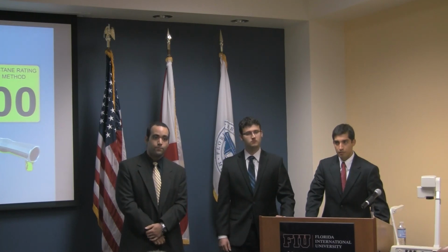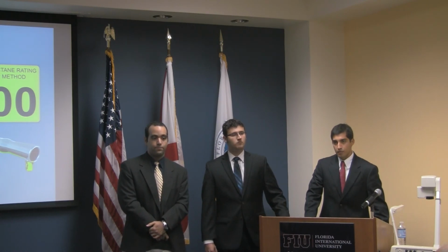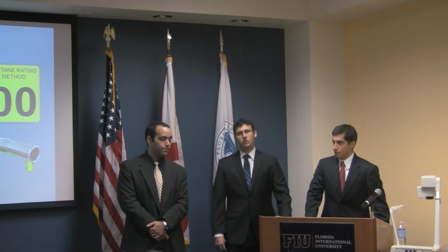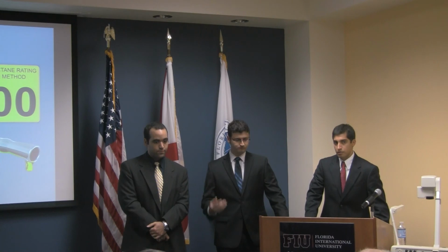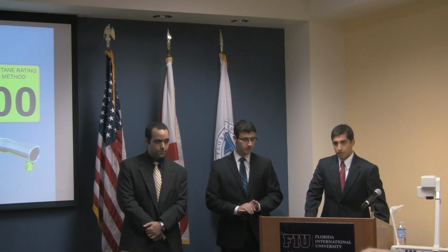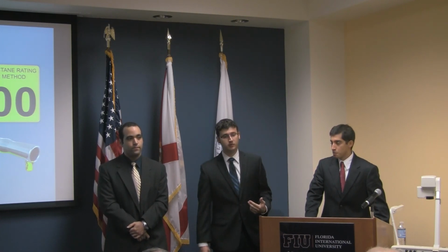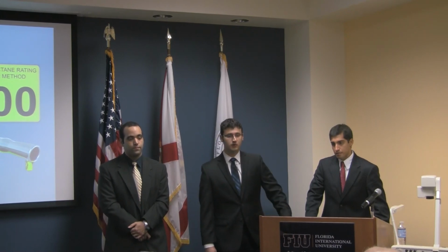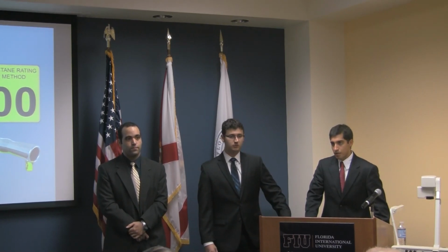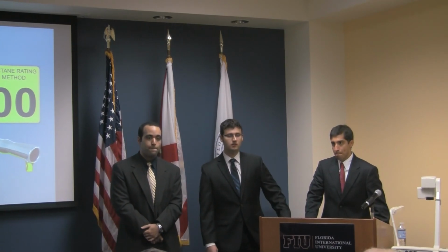Quick question there. So you found it a better option to increase the stroke as opposed to increase the bore? Yes. We chose to increase the stroke. A large portion of the design was that, well, you can increase displacement two ways. You can increase bore and you can increase stroke. Increasing the bore will increase your displacement, but it won't do anything to increase our compression ratio. Increasing the stroke, on the other hand, does, which is why we're focusing on it. Our primary objective is actually to increase the compression ratio. The displacement is just incidental.